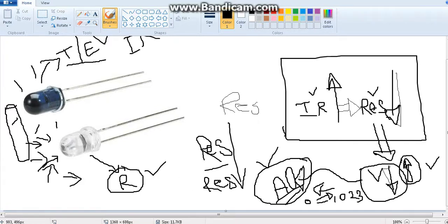We can calibrate and find out: less voltage value, less analog value means resistance is low, which means more rays are falling on the sensor. If the voltage is increasing, it should be the other way around.